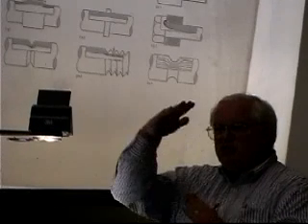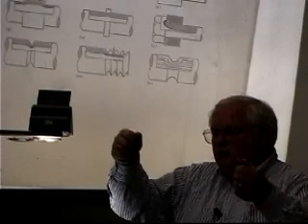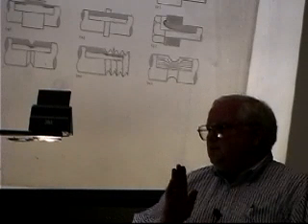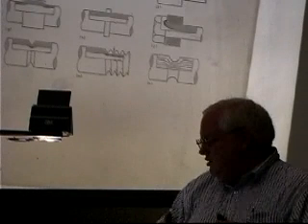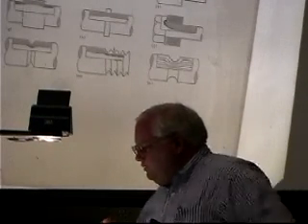Okay? If it was a knife edge, if you lay down a sheaf of papers on top of a knife edge, you'd have a big stress concentration right there at the knife edge, right? But it would die off to the side. If you kind of learn to visualize that, you don't have to solve Laplace's equation, you can just estimate it.